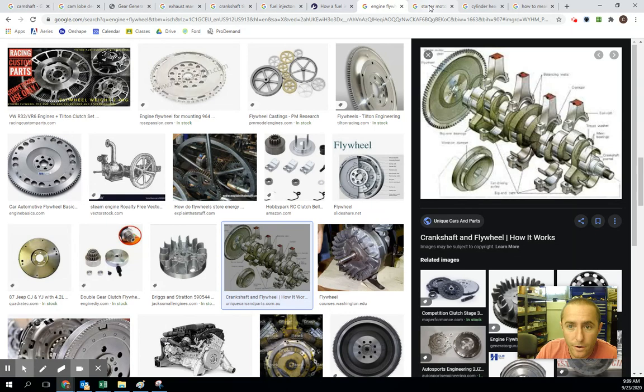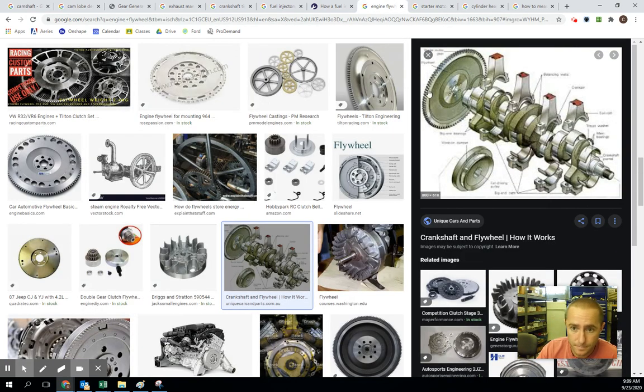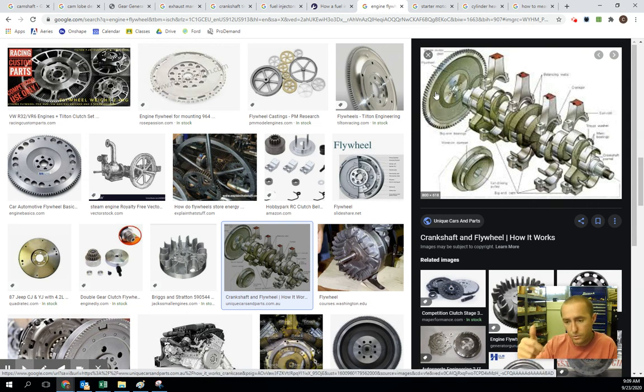So what happens is you typically have a starter. You have a starter motor like this, a small little gear here, a very, very high torque motor. That's hooked up to your flywheel or flex plate along those gears right there, and that starts your motor. We've turned over a car. You hear that, and then the car kind of starts up. That's that flywheel getting going. It's drawing in air and fuel, allowing exhaust, getting the whole gas motor to take over until the motor can just run smoothly without that. So that's one of the primary reasons for having a flywheel.